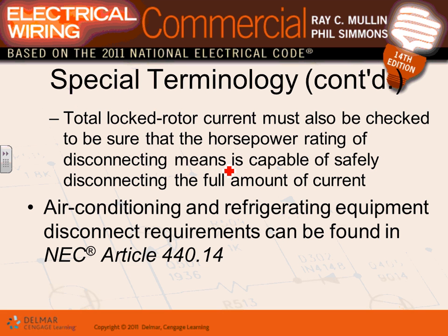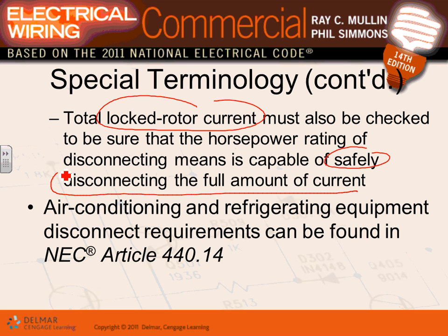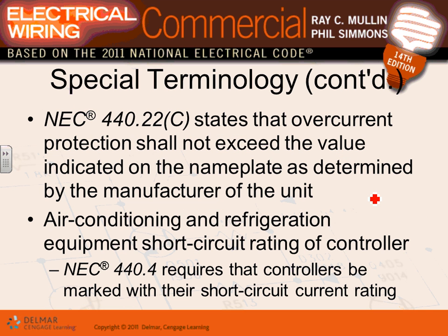One more time. It is very, very important, guys, to size the disconnect based on locked rotor current and horsepower rating. Why? To safely disconnect under full load current. If you don't size it based on horsepower, if you are to open it under load, it could explode in your face. Safely disconnect the full load current. So you need a disconnect.